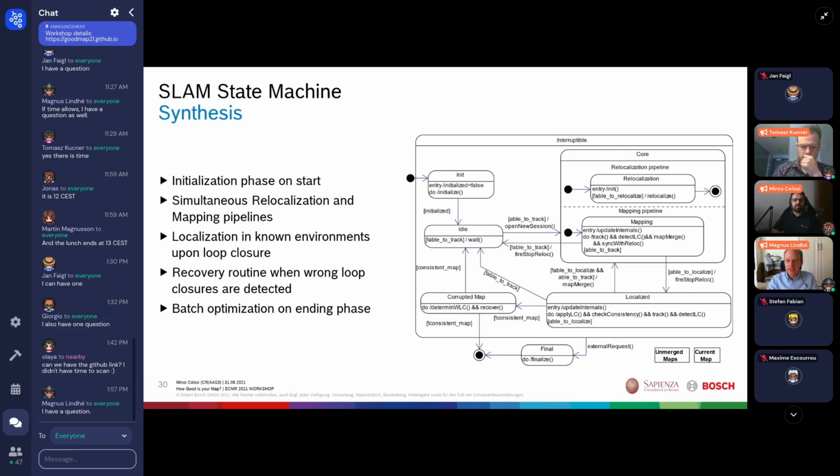I agree. I'm just saying that sometimes if you get lost, SLAM, I guess, or this state machine needs to take over. You need to actively relocalize, but in many cases, you can just passively observe and maybe do some optimization of the maps and loop closure. So I still think it would be an interesting extension if you would categorize that some states here are passive and some are active. So you actually need to take over from the target behavior and focus the whole behavior of the robot on relocalizing, because those are two different macro states to me. That's a really good point.